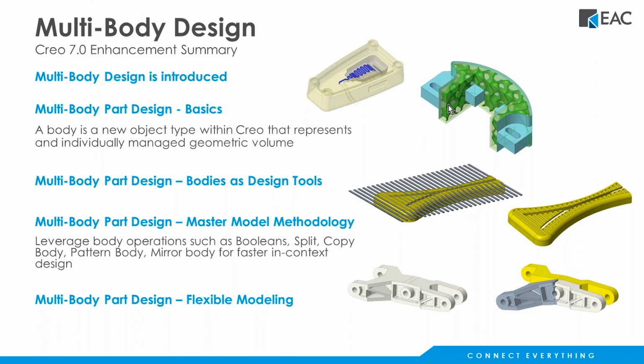Here's an example where we're taking one of the bodies of a multi-body and using the lattice feature, for 3D printing. Here we're just taking part of it and saying I want to create the lattice in that portion of the body. Here's an example where we have two bodies, I don't know, a bike seat or something similar, and we want to cut a series of slots in it. In this particular example, these are two different bodies. There's a yellow body, and then this one body was patterned multiple times. And then it's subtracted from here.